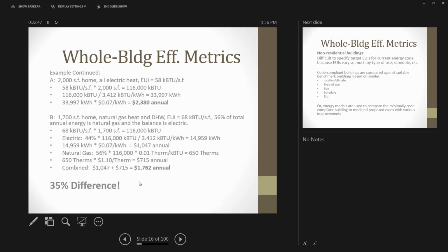So for example, if we're looking at these two houses and we're called in to do energy improvements on these houses, in House A, we'll keep it simple, if we're going to go in and do some air sealing and some insulation and it's going to cost us $900 and it's going to save us 15,000 BTUs, it's going to reduce our energy intensity and save us $300 annually, we're going to get a payback of 3 years before those energy improvements start making money.